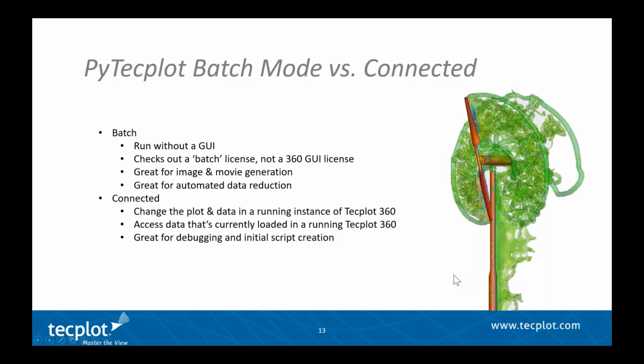Okay, batch mode versus connected mode. So this is an interesting one. Most Python modules run pure Python. Well, our PyTecplot allows you to not only run pure batch, but you can actually drive a live running Tecplot 360 with Python. So let's talk about batch mode first.